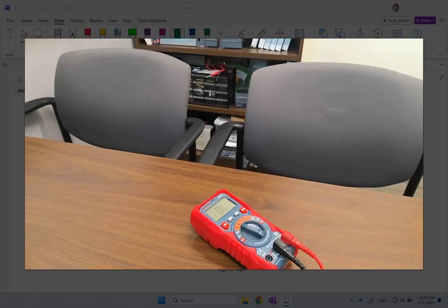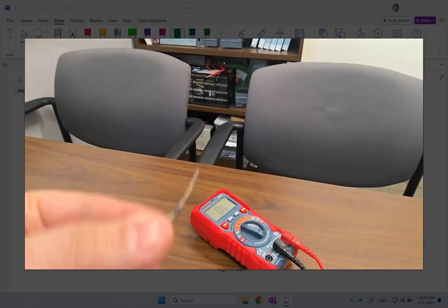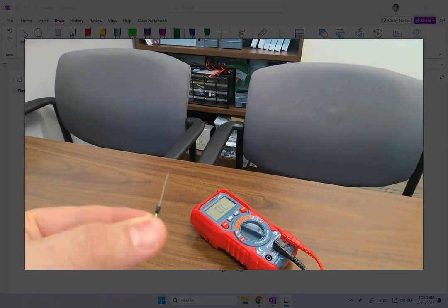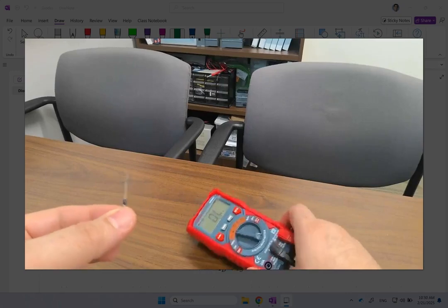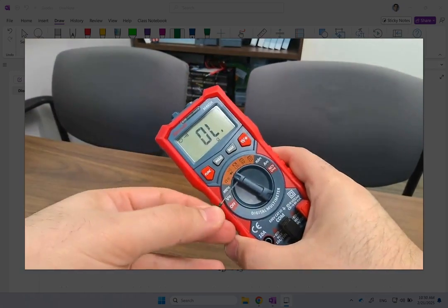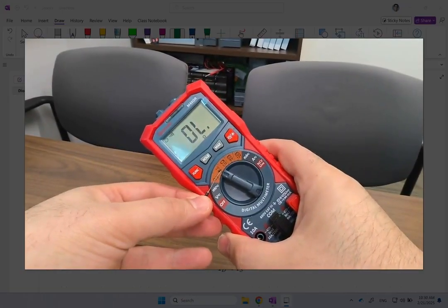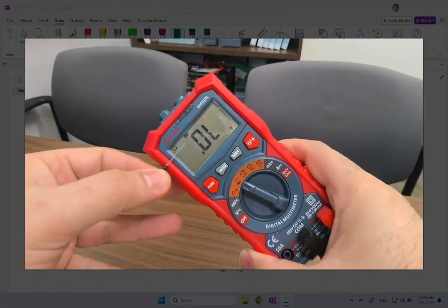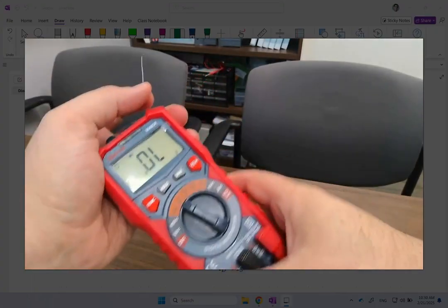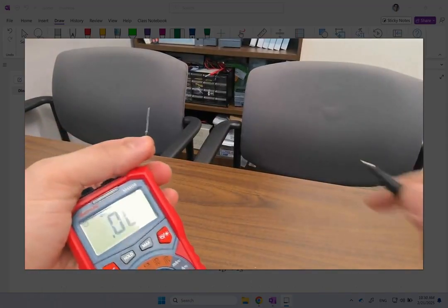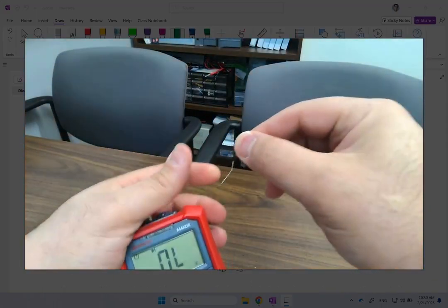Okay, to show you that in practice, here is a diode that I have. And this is my multimeter, and you can see that I put it here on the diode, and then you have to click on the function, so it shows the diode symbol, as you can see over there. And then, as I said, now you have to connect. Okay, so here we go.